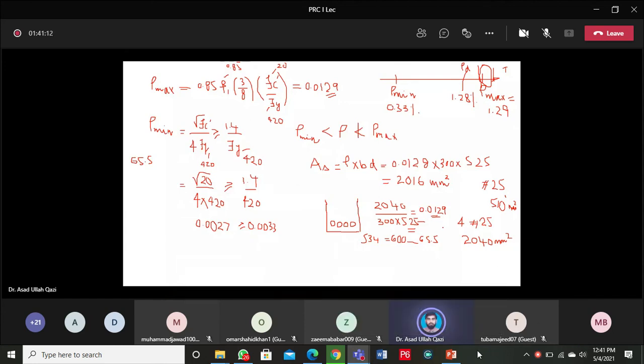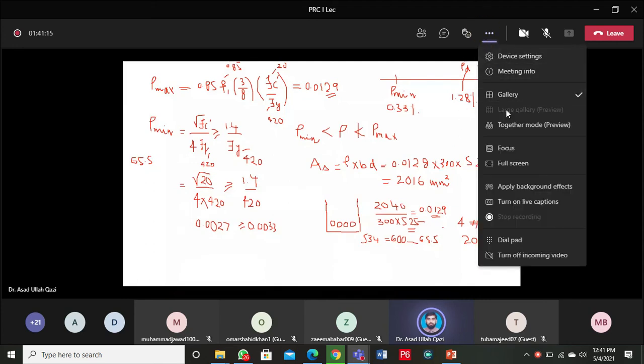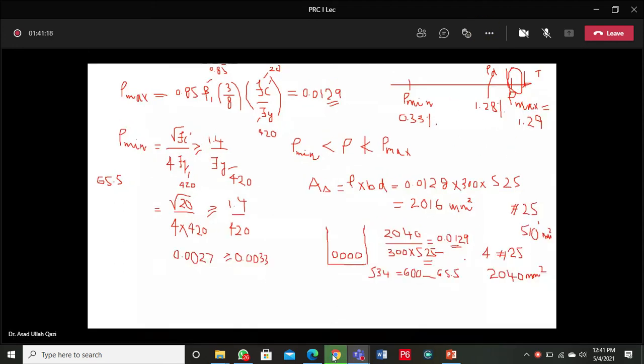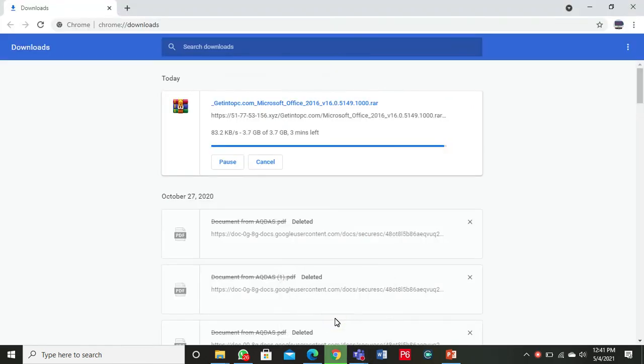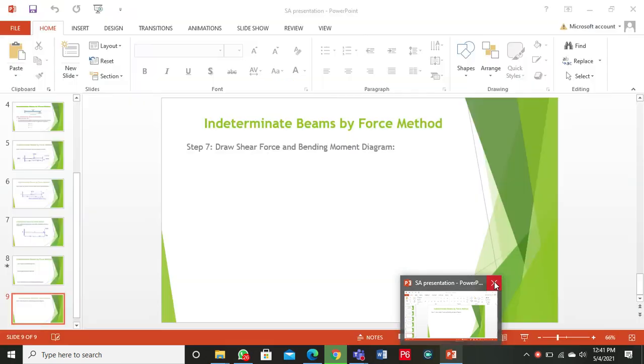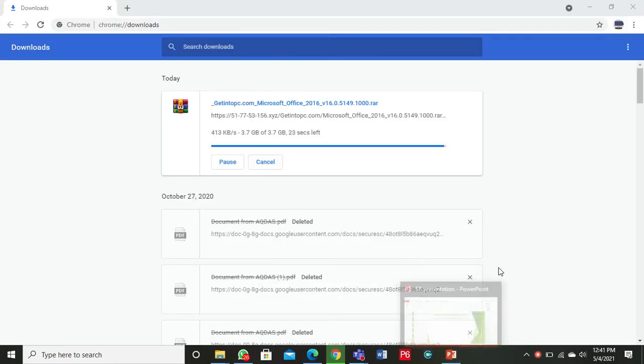Any effective depth less than 525 is dangerous, because it will result in a compromise on my capacity, because my lever arm will be affected and my rho will increase. So this is what I want to explain, that while making a final sketch, you must be very careful how you place the bars in one layer, what actual covers are in the field versus your theoretically calculated ones on paper.